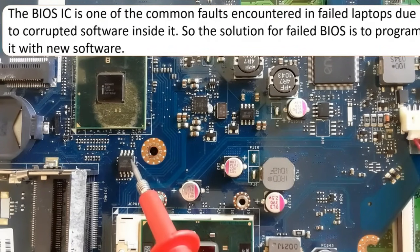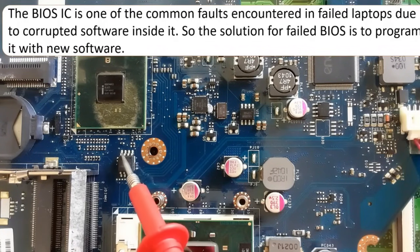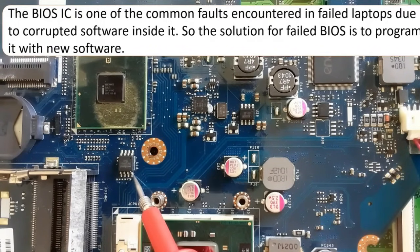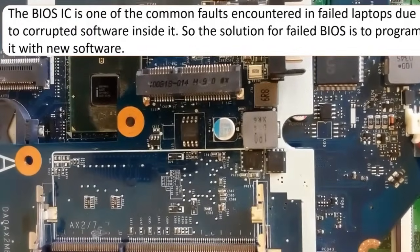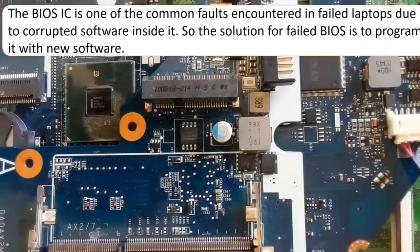Here we have this mark, which means pin number 1. This dot means pin number 1, then 2, 3, 4, 5, 6, 7, and 8. It's the same working principle. Here we have pin number 8, where you should find 3.3 volts when you power the motherboard. So the BIOSes in the motherboard have the same working principle.